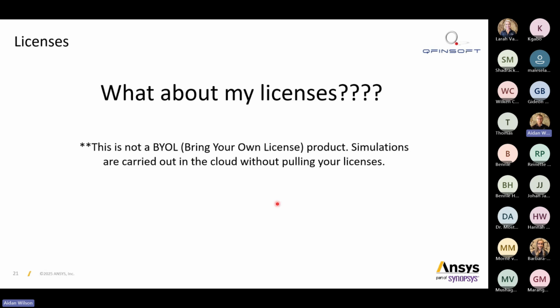It's because I've now gone and put it on the cloud. It runs with its own licenses on the cloud. So essentially, cloud is like having its own licenses. We can queue a bunch of runs. What's nice about this is I can send my simulation to the cloud, and then open another instance of Mechanical and start setting up my next simulation, and possibly solve locally as well if it's a different simulation, a different instance.